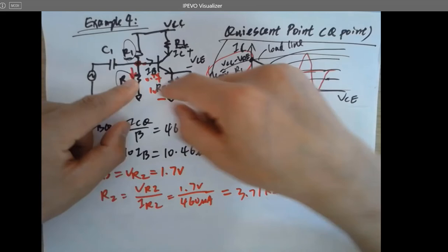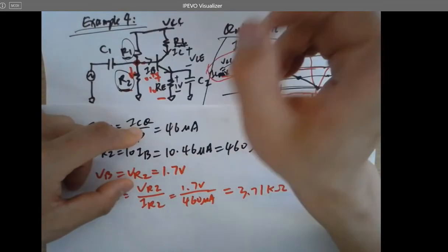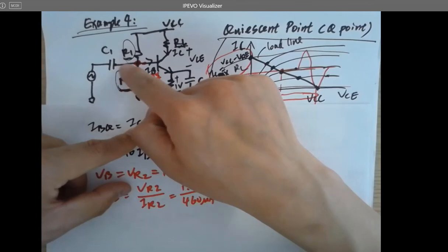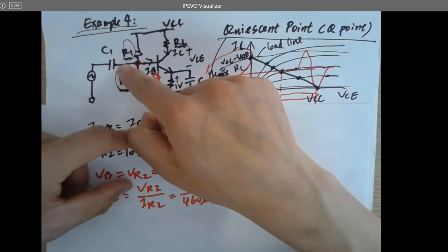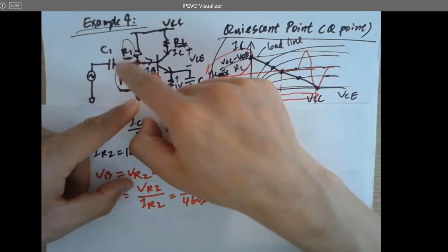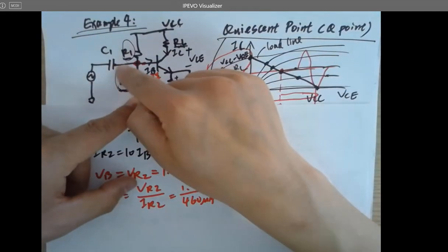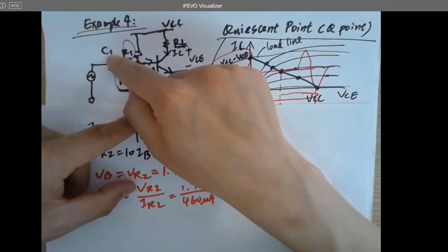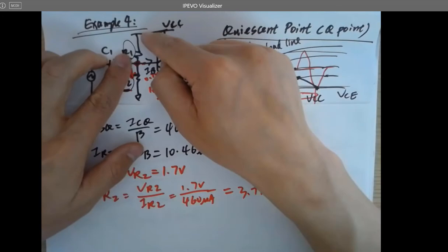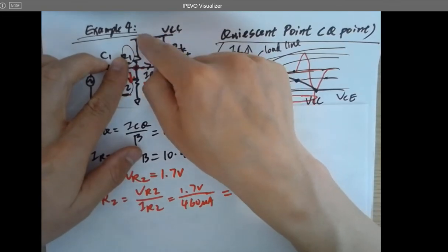Since we are talking about DC biasing, there's no AC current. So what's the DC current that flows through the capacitor whenever it's stabilized? Turn on the switch for a while. After a while, what's the DC current that flows in that branch? DC, 0. It's an open circuit. So current flows through here from the source, right? The source is providing a current.